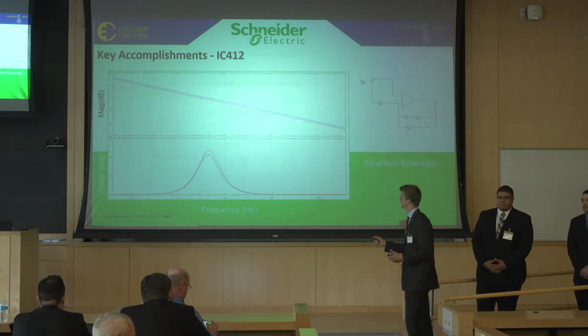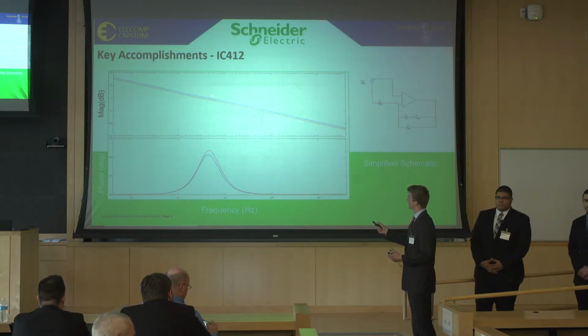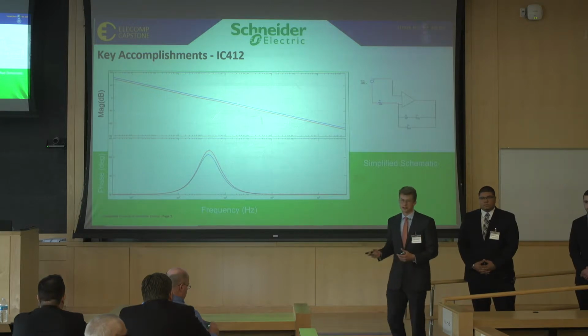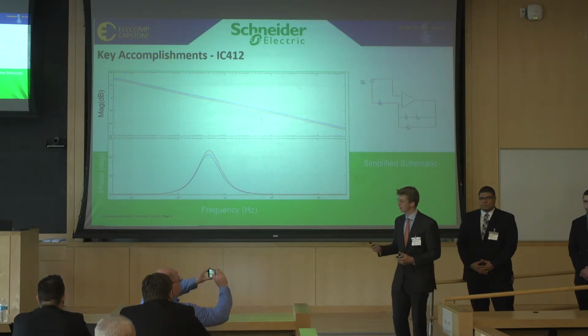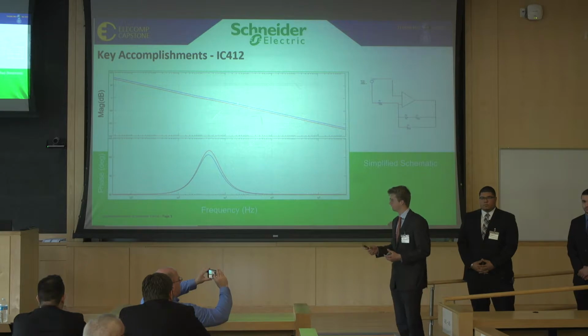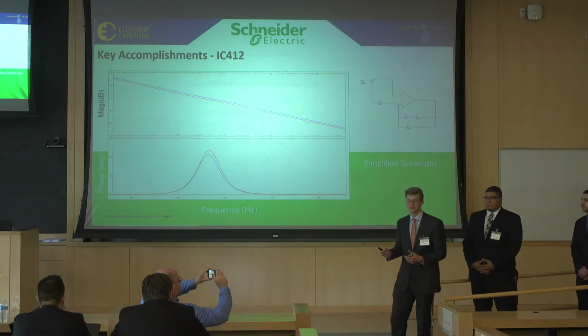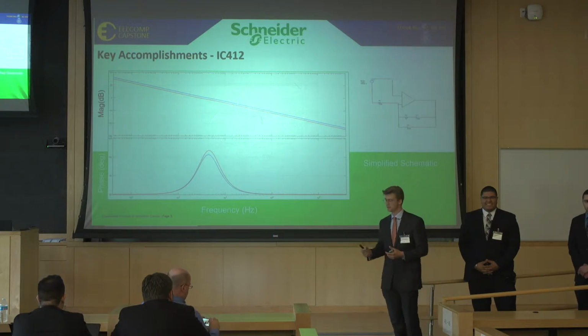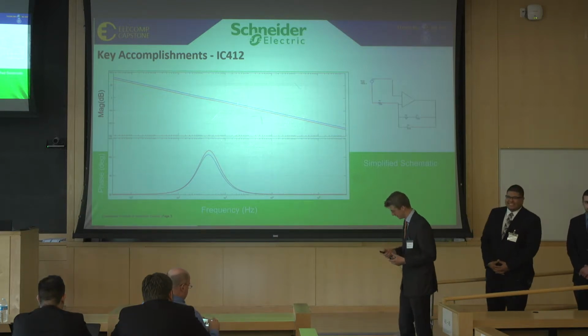In this graph specifically, the original circuit is in blue, and then our circuit is in red. You can probably see they're not exactly the same, but that's because we didn't use standard components. And that's just one thing we learned, is that you can't hand tailor every circuit. You need to use standard values. It's just a lot more practical.